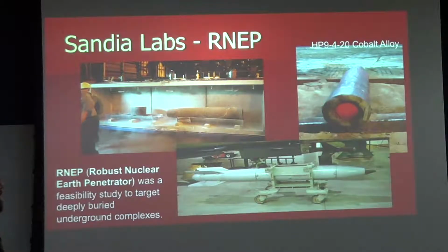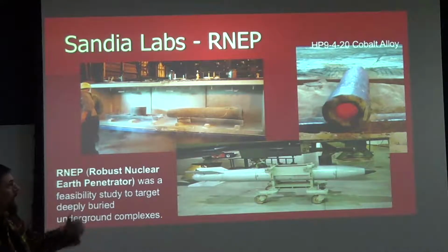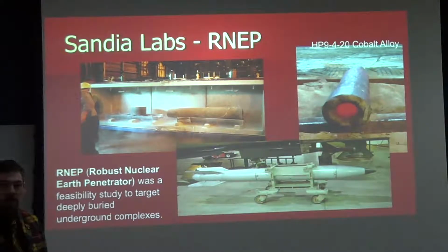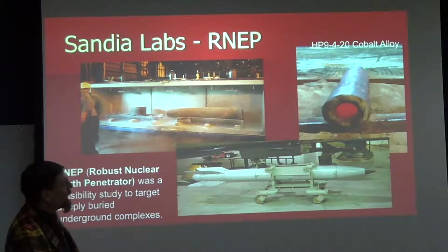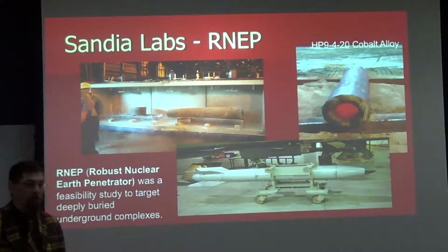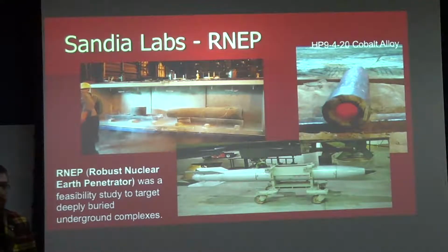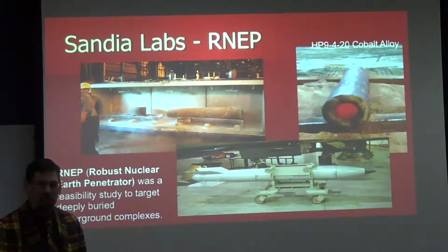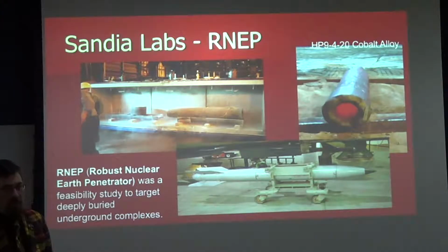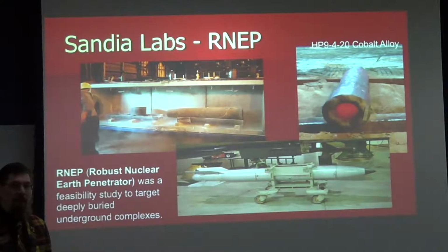What's the top picture? Is that a cryogenic chamber or something? Right, so that's being put through a cryogenic cycle to do some changes to the microstructure and properties. Is that done in-house, or do you have somebody else? We don't really have the ability to do cryogenic stuff in-house. The closest we've come, Alex may have gone back to school before we did it, but I had some parts that I ran through a dry ice cycle. But that's not really a true cryogenic treatment.